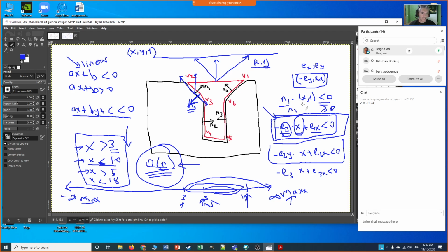But as I said, you probably got the idea anyway. So we want the angle between these two pulling vectors and the normal vectors to satisfy a valid pulling direction. We just use a dot product of these two vectors, which gives us a linear constraint. That's the key. All right.